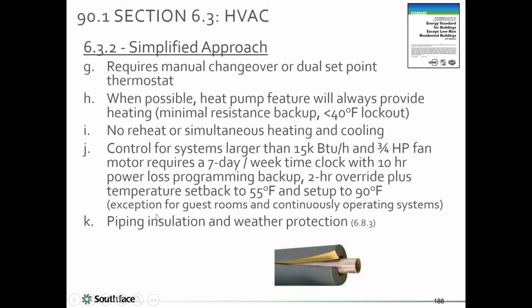So pipes need to be insulated and protected from the elements. I've seen suction lines on equipment on the roof of a split system, suction lines that were running along the roof. I was up there, it was 92 degrees, and all of the pipe insulation had just dissolved. And here it is running across this hot roof, and you could put your hand on it and it felt nice and cold. And you're like, that can't be good, because the insulation had just dissolved to dust.